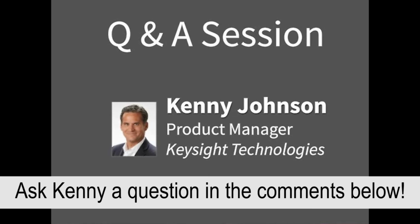So not only do we use it to perform calibration on the instrument, where we'd store off in software some calibration factors about the probe, but you could also find out that if you can't get your probe to pass the user cal, then your probe is deteriorated. So first, make use of the user cal.